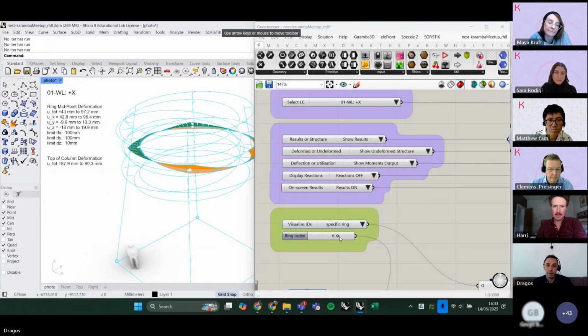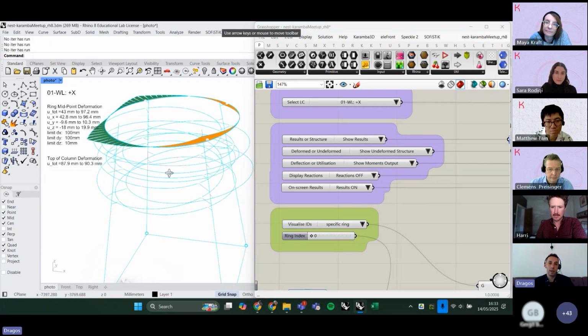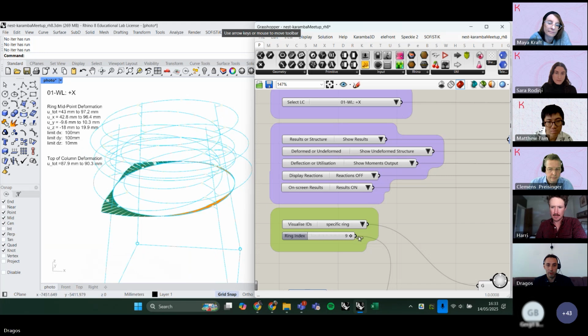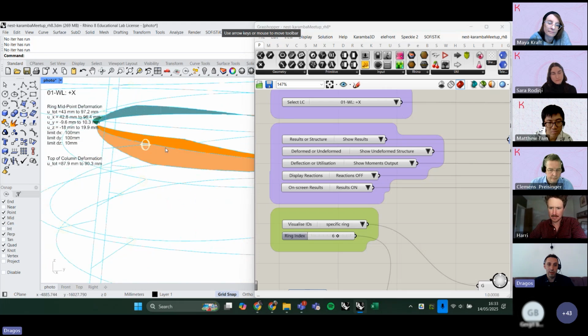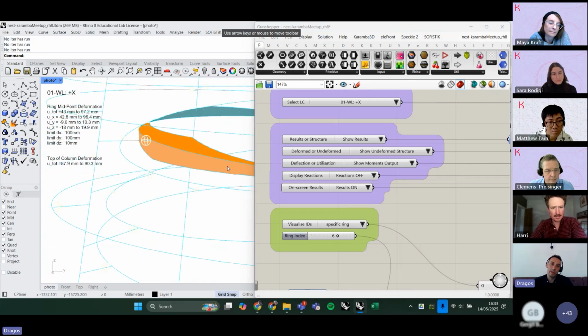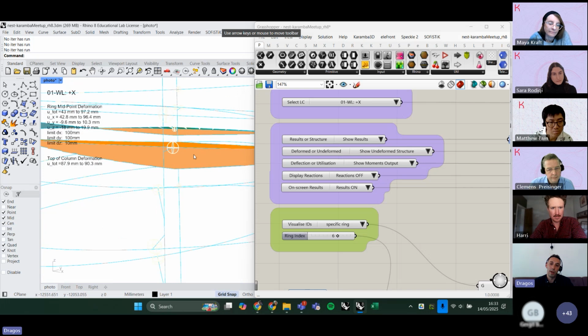And this is where the story about the fixities is relevant. Let's have a look at one of them. Let's choose a good one, maybe this one. So you see, this is the glulam member. This is the connector arm, and it's rotationally free around its own axis.